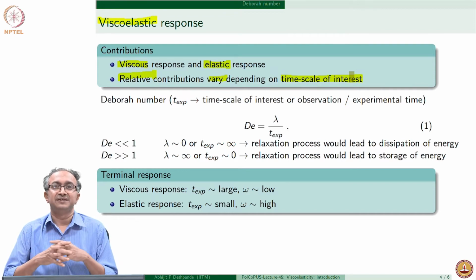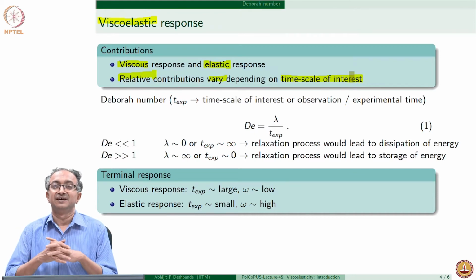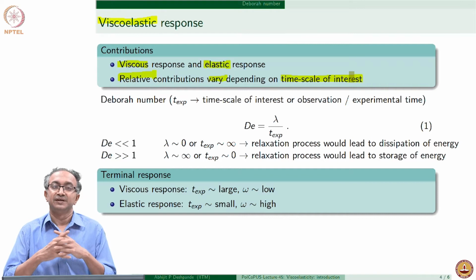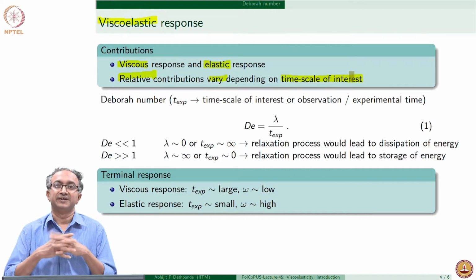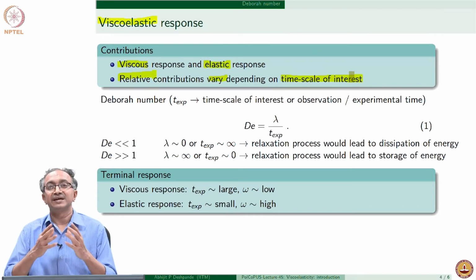So, therefore, for certain design of engineering polymers, we may be able to assume elasticity because that is the time scale of interest that we are working with, and those are the numbers with which we will do our design. It does not mean that the material itself may not be showing some viscoelastic aspect, but the overall practice of engineering and technology happens in such a way that we can get away by assuming elastic response. Same thing is true about, let us say, transport in huge pipelines of materials which are non-Newtonian or viscoelastic fluids. Again, there we can assume that they are largely viscous fluids and again get away with engineering empiricism. However, that does not imply that the viscoelastic melt itself is not showing any viscoelastic behavior.